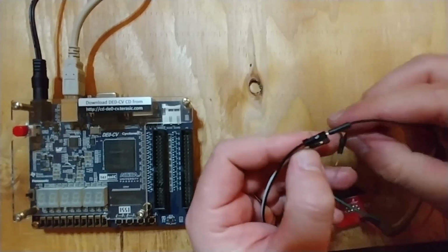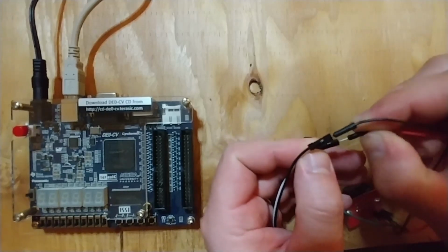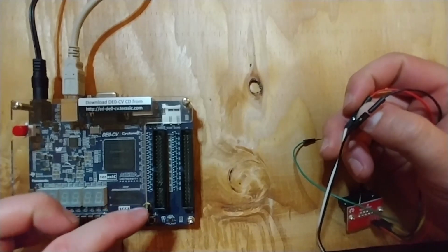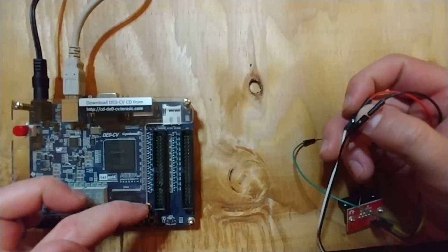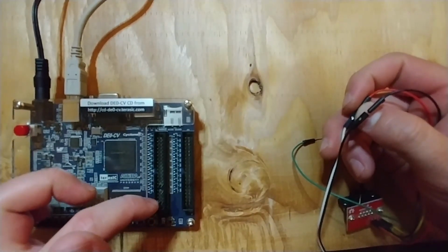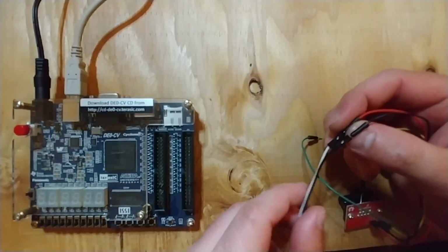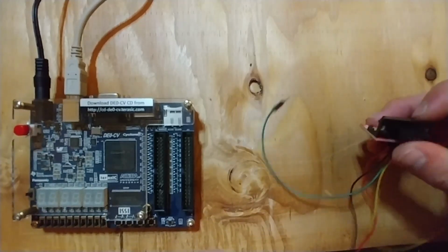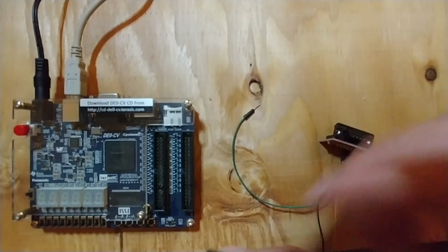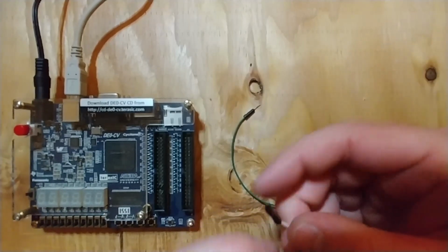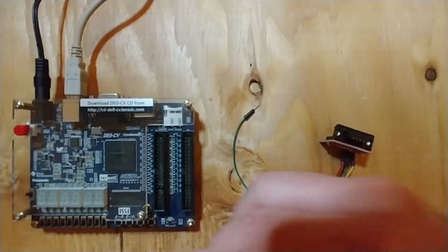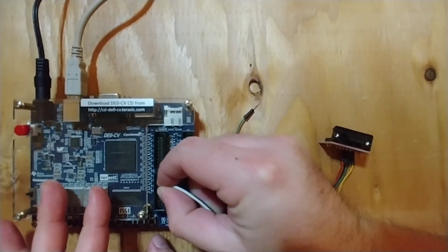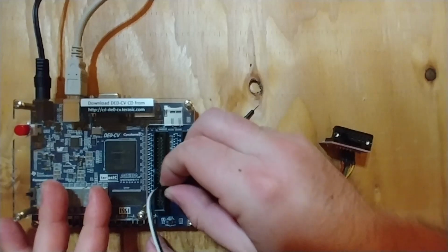Okay, and then 3.3 volts and ground were actually the 6th pin up from the bottom. So if I'm looking on the header and I count up, 1, 2, 3, 4, 5, 6, that's where I'm going to want to connect my ground and VCC. On the left was VCC, which is the red, which is mapped to white. Again, not really my druthers, but okay, let's count. 1, 2, 3, 4, 5, 6. All right, and then ground is right next to it.